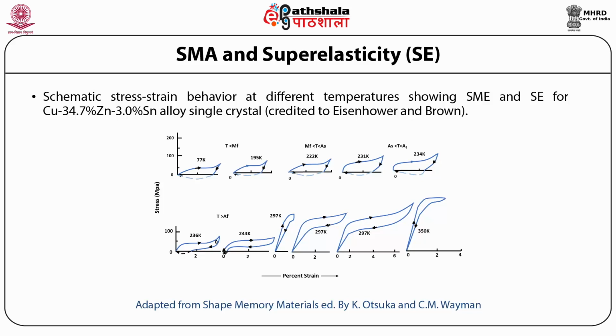Here again we see two distinct behaviors at temperature below MF and at temperature above MF. At temperature below MF and also below AF, as long as the starting material is in martensite phase, upon loading and unloading, the total strain is not recovered.